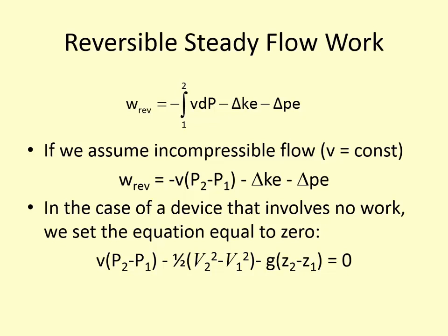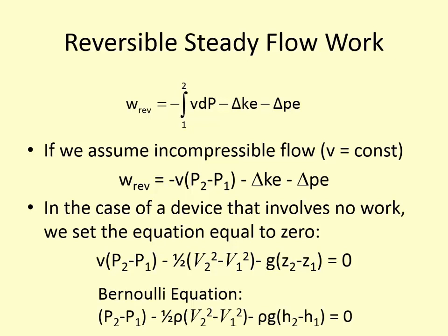Okay, this is an energy balance, right? Energy equation. But more specifically, this is the form of the energy equation that's often used in fluid mechanics called the Bernoulli equation. And it's derived in much the same way, starting with energy balance. The Bernoulli equation also follows the first law of thermodynamics, which is that the energy components of the system have to equal out. So in pipes or flow networks where there is no work added or consumed by the system, it's just a flowing fluid, the relationship between pressure and velocity and any elevation change is given by the Bernoulli equation.